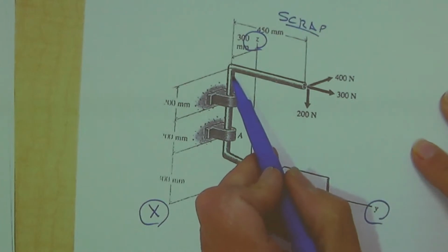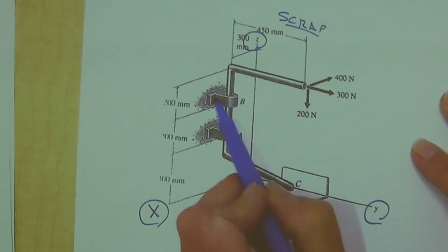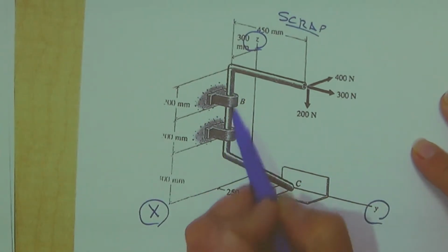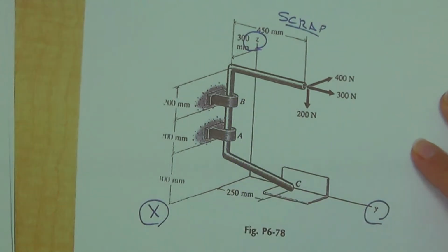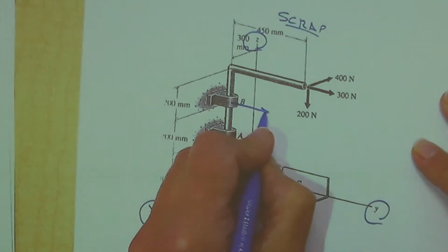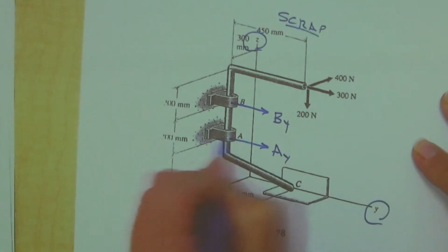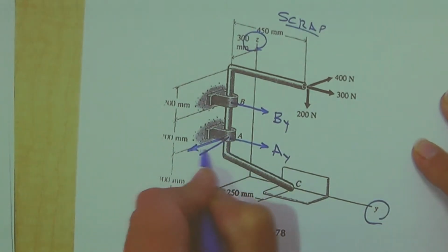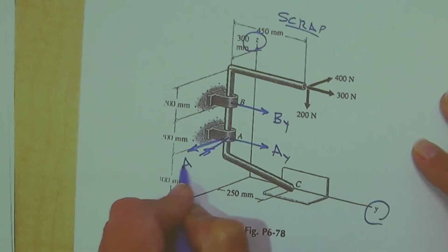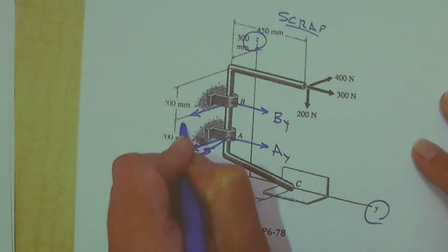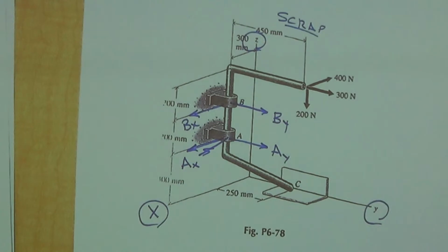Z, because we're looking at the connection between the bar and this collar here. The bar can slide up and down the collar. So which force reactions does it have? X and Y. So should we call it BX, BY, AY, oops, AX, BX. Does everybody agree with that?